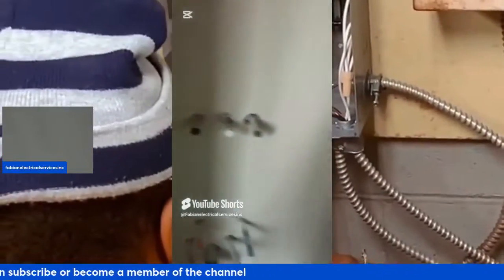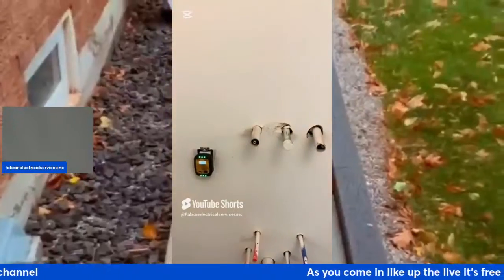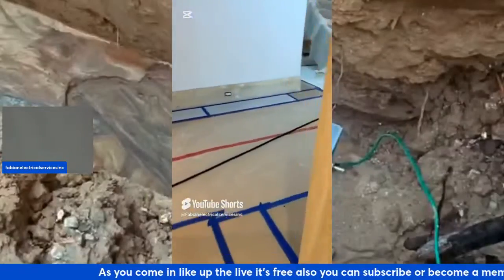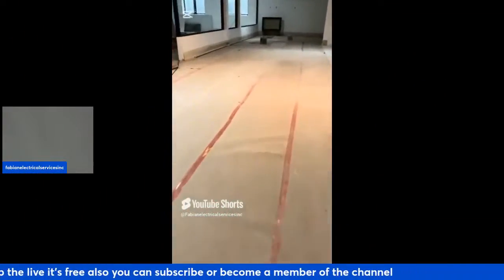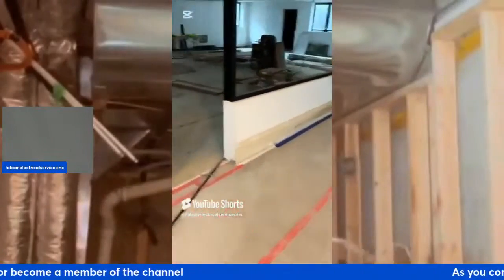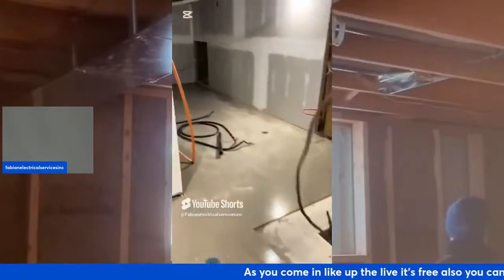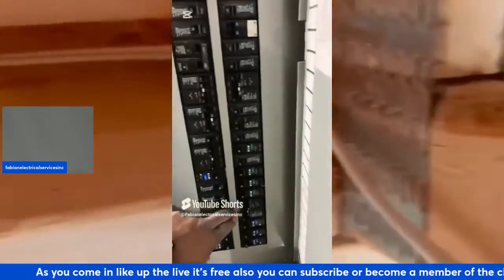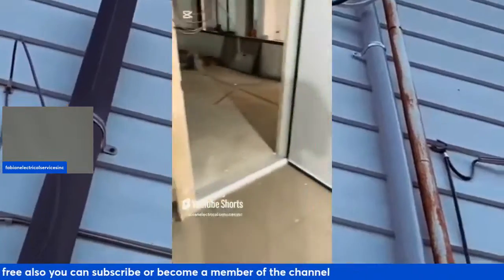So a lot of times, 100% of the time in homes where we are located, I'm not sure what the difference is in other countries, we have to put arc fault protection throughout the home on most circuits, except for your kitchen 20 amp countertop receptacles, and so on. Your fridge doesn't call for one.